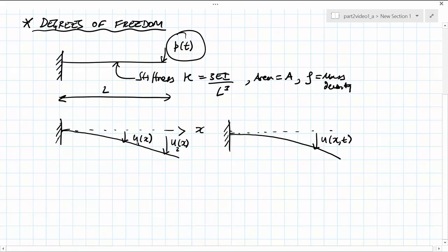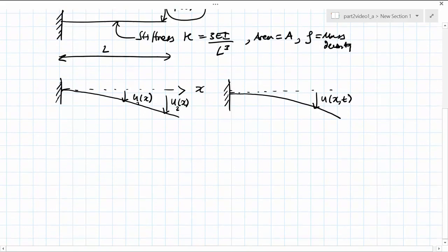The exact and more complex way of analyzing this type of structure for its dynamic response is to set up what we call a continuum vibration problem. However, we can simplify things by adopting what we call a single degree of freedom representation, where the structural system is approximated by a concentrated mass connected to a linear spring and a damping force generator that we will call a dashpot.